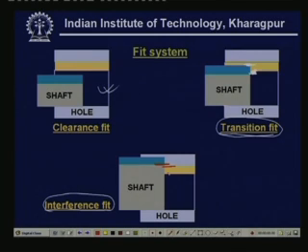Even if we go to the maximum size of the hole or minimum size of the shaft, there is always an overlapping in the basic sizes. So, that is what we call an interference fit. This interference fit could also range from a pressure fit to a tight fit.